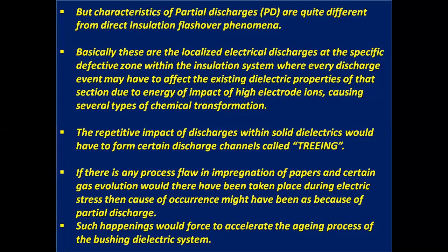The repetitive impact of discharges within solid dielectrics forms certain discharge channels within the insulation, which is called the treeing effect.